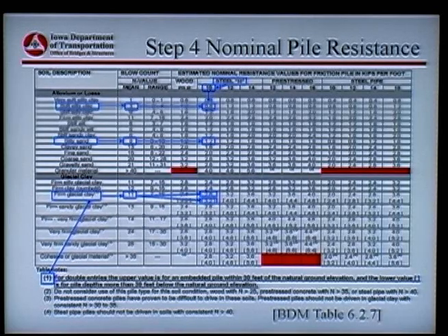And we're going here with the silty sands. It was a loose sand in here with a blow count of 8, and so we got 1.2. In the same token with the firm glacial clays, it's medium stiff in here, and so we had 2.8 within a depth of 30 feet below the ground surface, and at greater depths it was 3.2, which is the number in brackets.